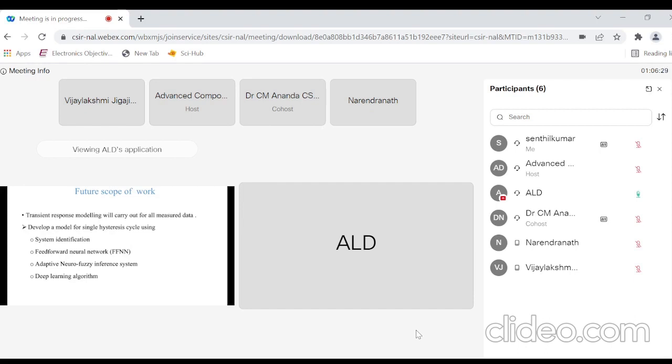Now I'm going to the next question. What is the basis for taking 10 to the power of 3 data points? Initially we are taking 10 to the power 3 data points for the initial stabilizing part, that is the transient part. For the middle section we are taking 10,000 data points, and for failure also. What is the basis? Why 10,000? For lower frequencies you can take 1,000, and for higher frequencies you can take more.